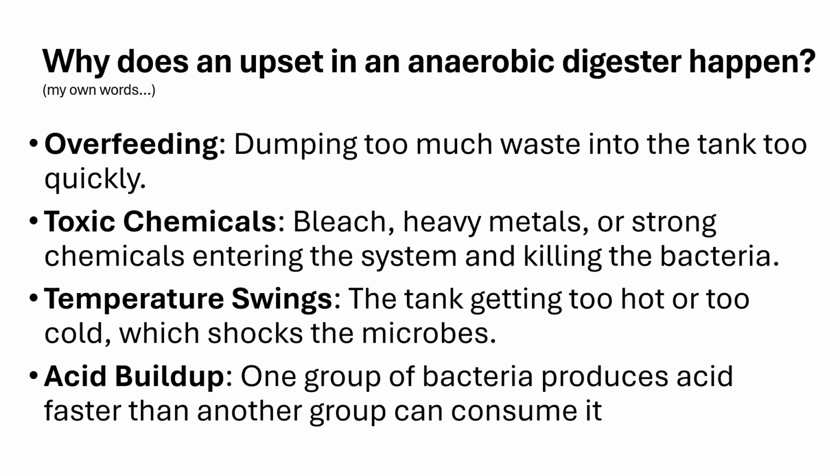Okay. Why does it happen? We either overfeed it. We dump too much waste in the tank too quickly. It's like eating too many nachos or hot dogs or beer at the Bronco game. Or something toxic to those microbes, bleach, heavy metals, strong chemicals, gets dumped into the wastewater collection system and we can't catch it.